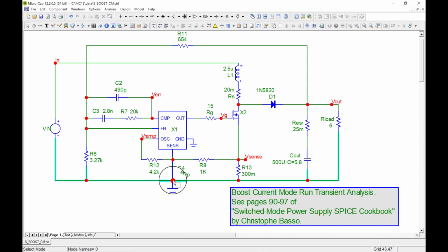See these four-way intersections? Guys, there's a thing called the art of electronics, and four-way intersections do not belong. So I'm just going to grab this guy, scoot it over. Got rid of that. No reason to argue about it. Just makes it easy to see where circuits are connected and where they're not connected. If this is connected here and that dot's gone because my circuit's really big and these dots get really small, then it may look like this wire just comes down to this resistor, this diode comes out to this load. But I can just move this over, okay? I'm going to make it look better, and then we'll talk about the circuit.